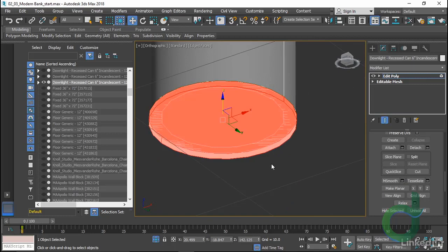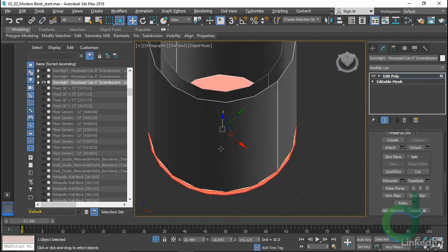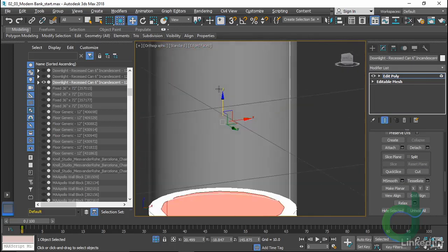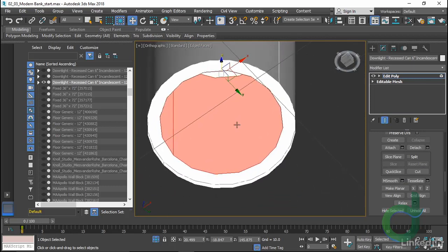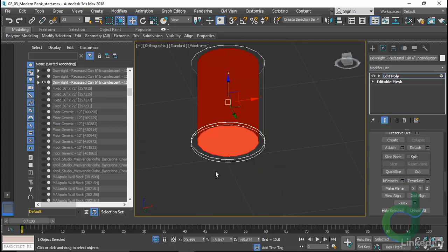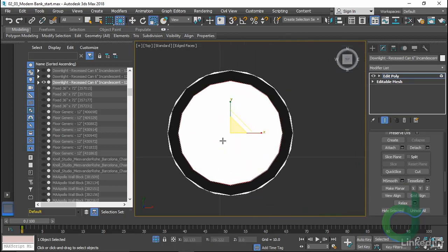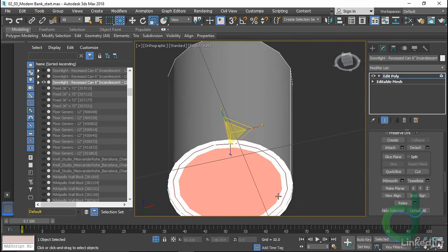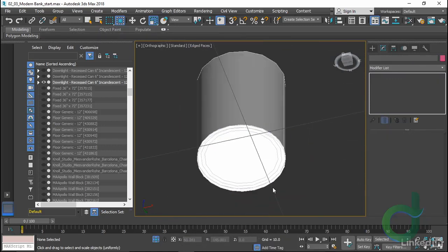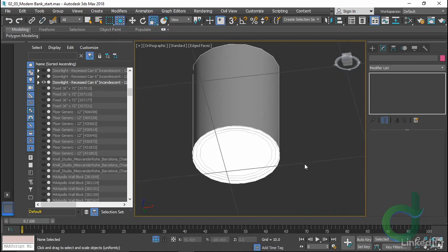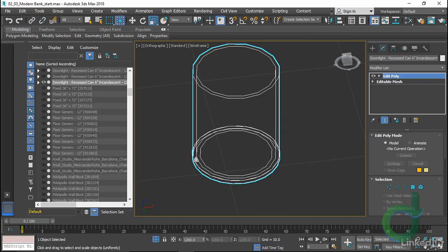I'm going to leave it on and put a glass material on it, but what I will also do is really shape the nature of this can a bit. I'm going to pick this element that's the inside here and scale it out. It looks like it's just this one piece. And so what I'll do in a top view, hitting Z to zoom extents, is press R for scale and scale just on the XY plane to make this piece a little bit bigger and the can light a little slimmer. This looks good. Whoops, hitting Z to zoom extents again. Now I've eliminated some unneeded geometry and slimmed this mesh down.